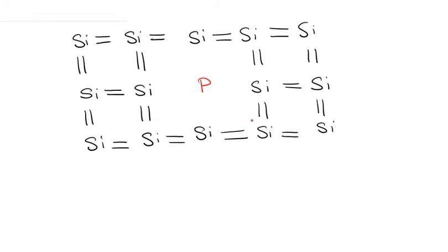It is very high actually for an impurity doping, but generally you introduce a maximum limit of 1% of phosphorus atoms. Okay, so you do not introduce, let us say, 10% of phosphorus in silicon, but you introduce a maximum of 1%, or a maximum of 2% in exceptional cases, in the silicon crystal structure.